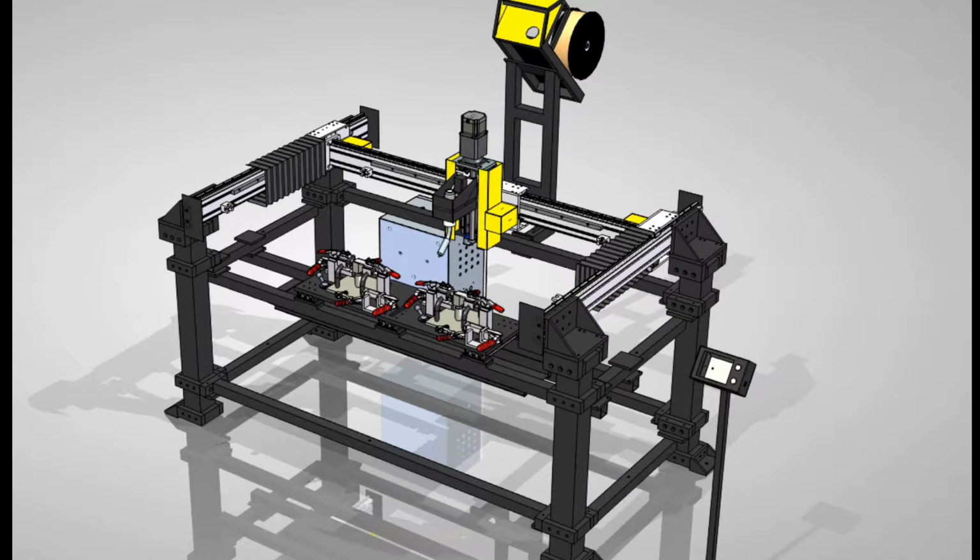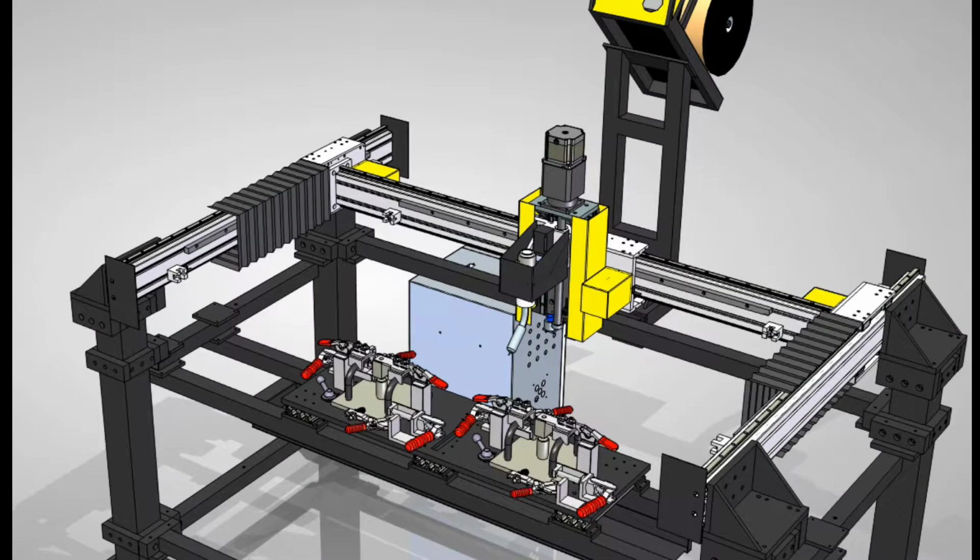Now if you look at the design of it, this was the first episode of how we design the entire stuff, or we call it DAP1, where the process goes into approval. If I zoom into it, you can see how we have placed two fixtures for welding the casting plates. What happens here is we have stage 1 and stage 2. Once stage 1 gets welded and the torch axis moves to stage 2, the stage 1 component is declamped and immediately a new component is loaded. So it saves a lot of time.